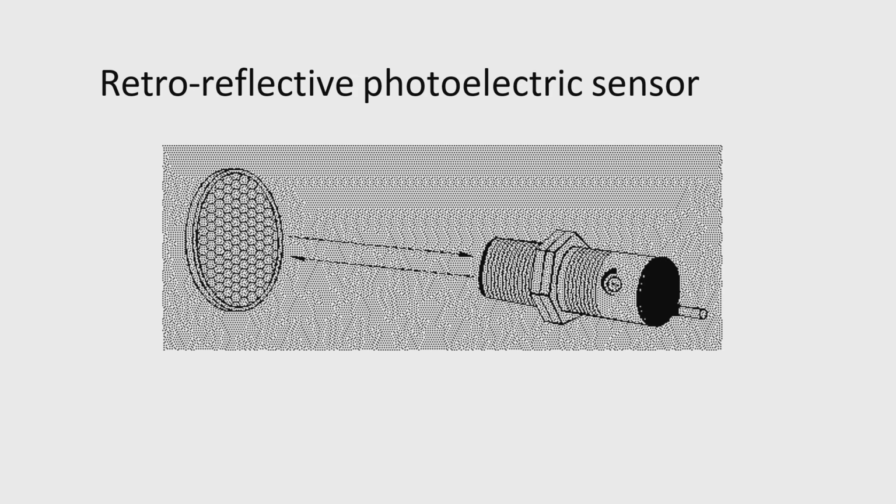And we have photoelectric sensors. We have seen such things, like when you go to some railway station, there is an automatic door which opens. So basically it senses your movement. One example is the retroreflective photoelectric sensor. Suppose it is sending some light, and there is a reflector on the other side which reflects it back. So it knows that yes, I am receiving that light back.